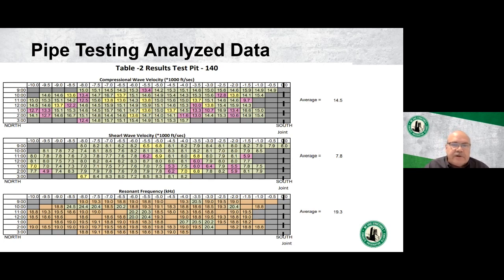Legends of green and yellow and red are often helpful to explain where the weak sections of pipe are, not only which section, but where within the section: 11 o'clock, 8 feet down, or 3 o'clock, 4 feet down from the joint, or whatever it may be. So it's very important to document the condition of the pipe, get the stations right, and know which section of pipe we're on. That's where some of the desktop inventory information can pay a lot of dividends.